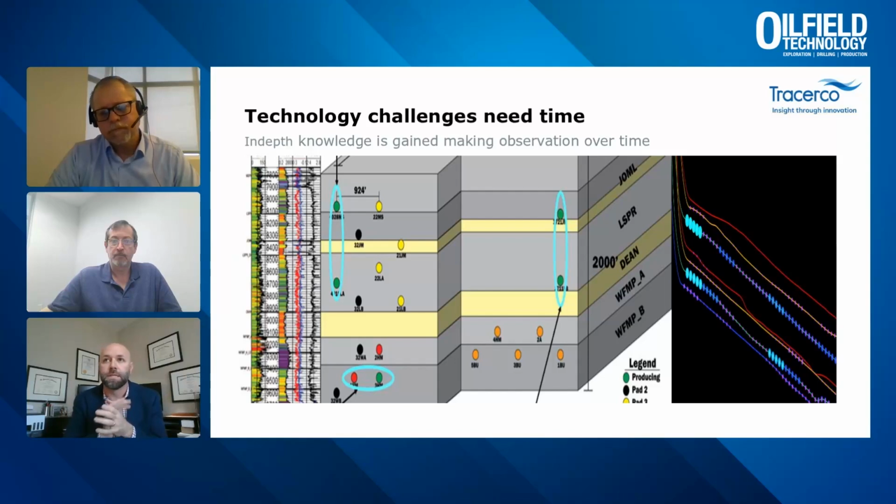Okay, another thing that's changed a lot, as we know, in the horizontal unconventional development in the U.S. is these multiple benches that are being completed, and looking at things like order of operations, which frac stages are completed first, stress shadowing, building a pressure wave to try to contain fractures within certain reservoirs, or looking at depletion. And we're able to look at all of that with tracer data.